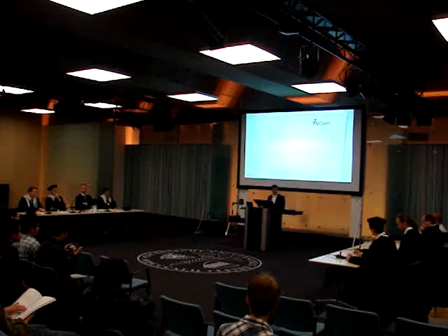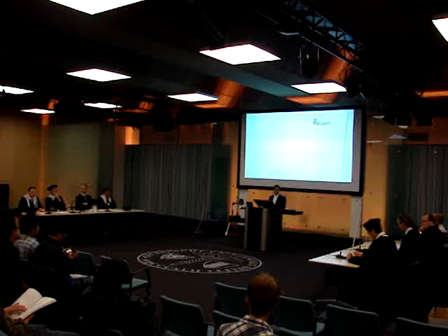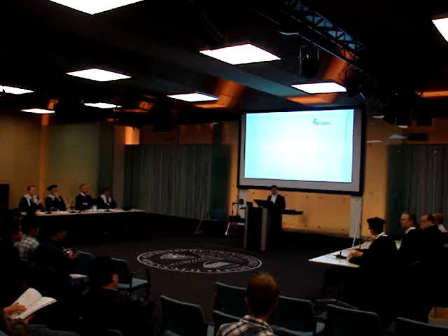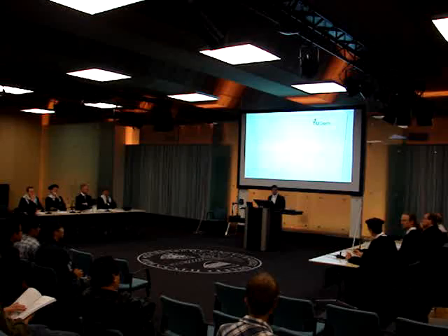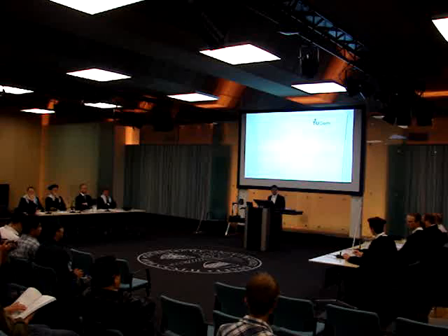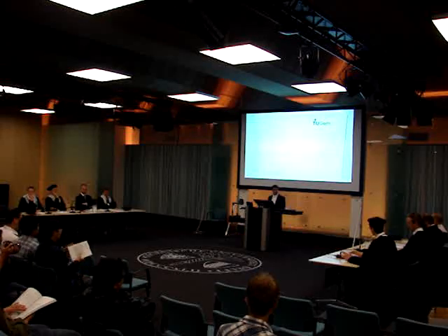Yes, thank you very much. I'm satisfied with this answer. Now I'm going to ask you a question about boundary conditions on the representative volume element. Essentially, with some periodicity and scale ratio requirements, the microscopic solution that you have should be representative of a full-scale direct numerical simulation of the global structure.